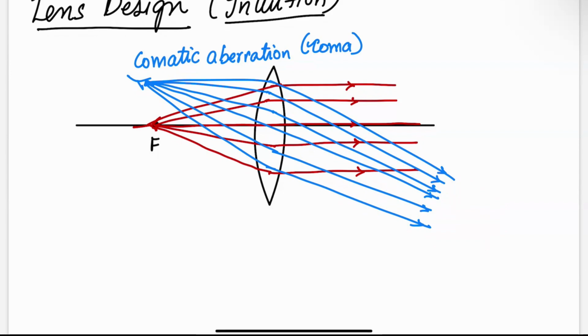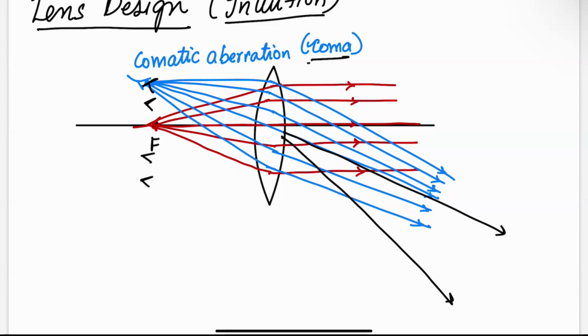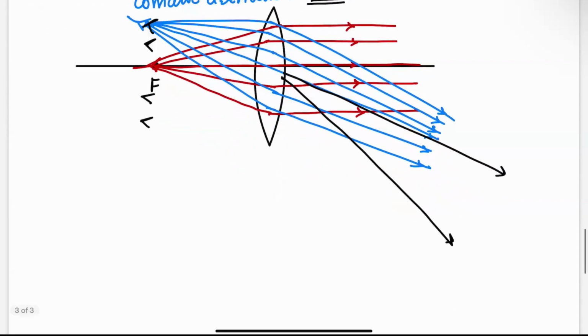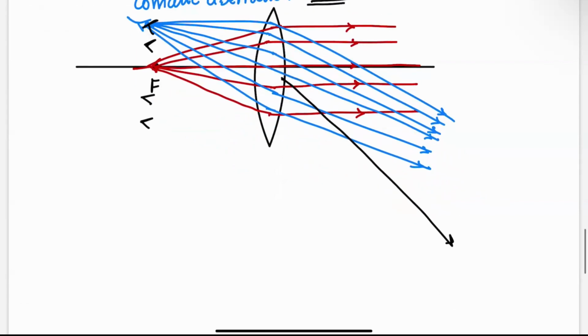And that's not good, right? Because you want to make a beamforming network. Let's say I have many antennas here. As I move away from the center position, the beam becomes broader and broader, right? So the beams that go this way become broader and you get some side lobes. And when you go this way, it becomes even worse, right? So the basic idea behind a Rotman lens is to fix this problem, to see if you can correct for this coma aberration by doing something. Let's see what that is.